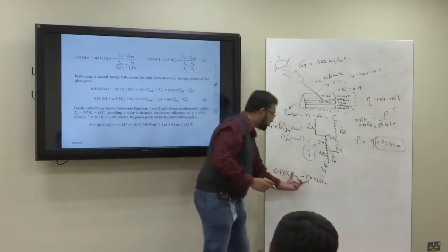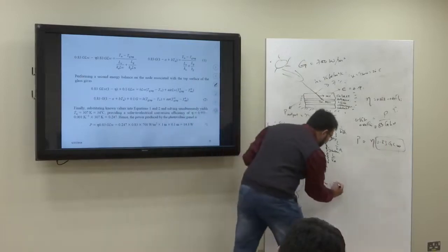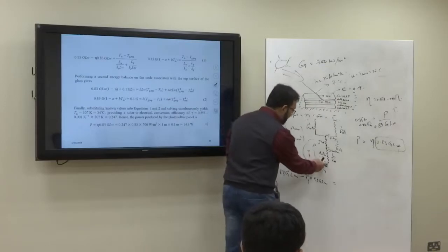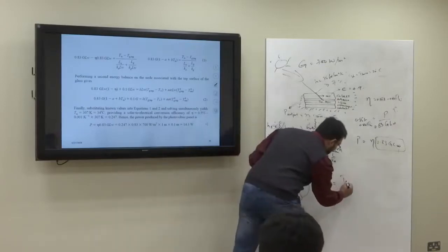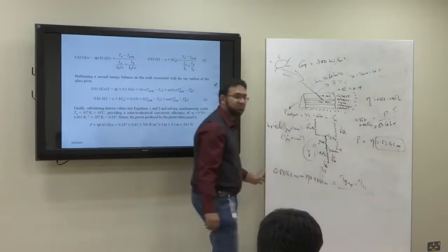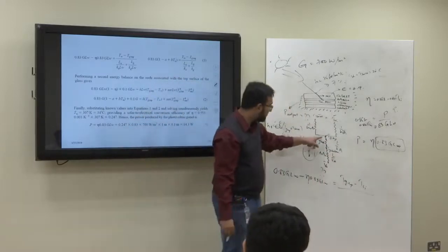This is Q, or this is the heat. So, the heat flowing is equals to the temperature difference from TSI to TG top. Okay. So, TG top minus TSI divided by the resistance in between. And what are the resistances we have in between? Two resistances.